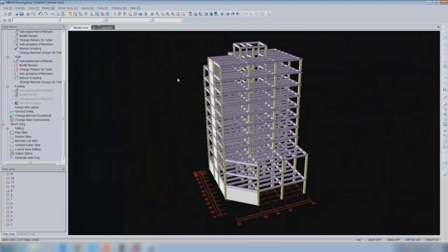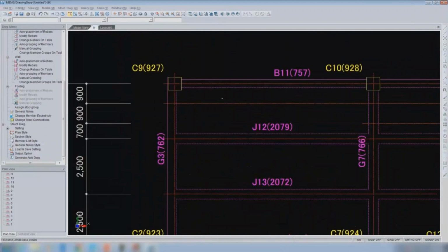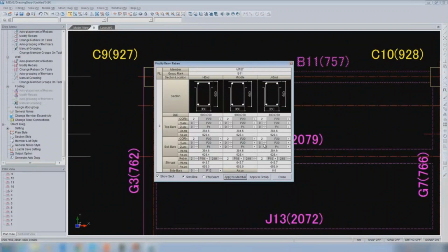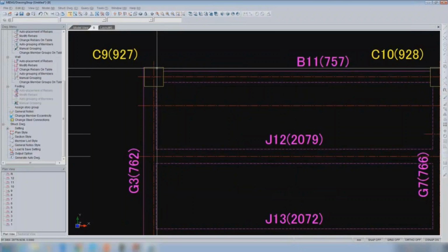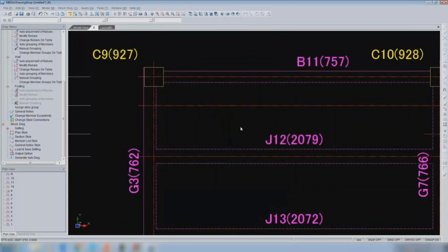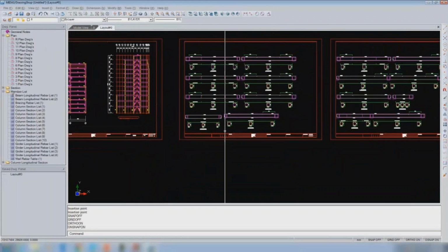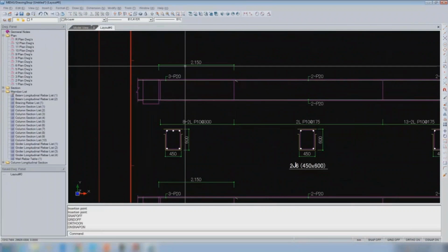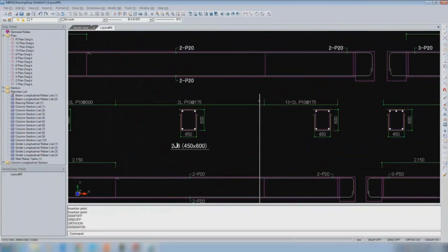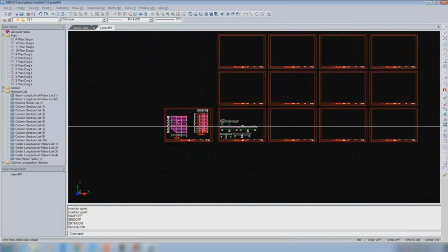And even in the model view, if I double click on this beam, then also you can modify your rebar. You just modify the rebar here and based on your rebar, it will give the drawing. So you can modify the rebar here itself also. Even for the column also you can modify. Just double click, it will modify the rebar, even stirrup and the entire thing. Based on that it even gives each and every bar length also. I mean this is the length we are using so that it is easy for the engineer to generate.